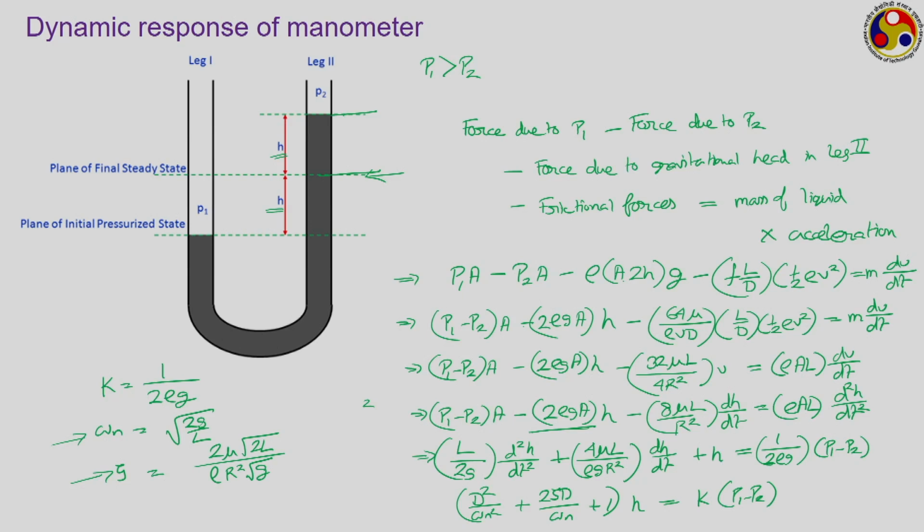Like a manometer which is initially under steady condition, maybe having equal height of fluid column in both the U columns, if it is suddenly subjected to some kind of ramp input or maybe just a step input, that is, suddenly you impose a different pressure on both the arms, then how is that going to behave? You can easily do this by comparing with the corresponding reference equation. So, that is it for the manometer. Let us quickly move to a few other devices.